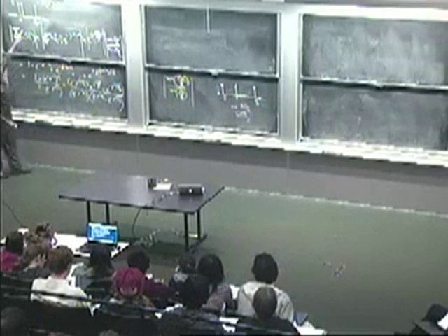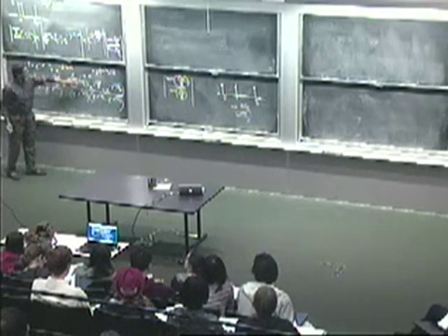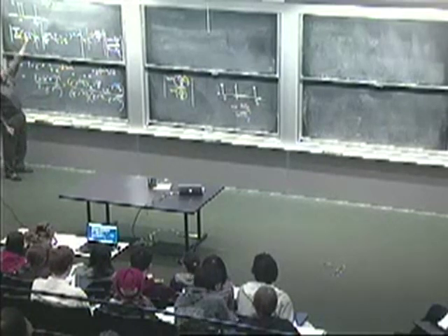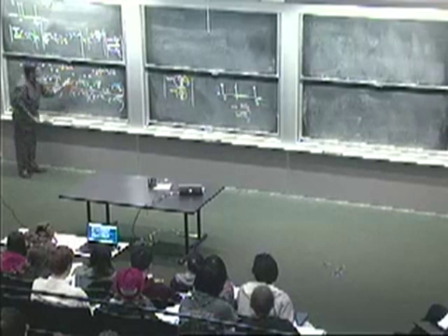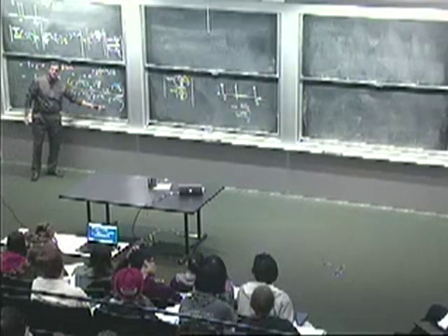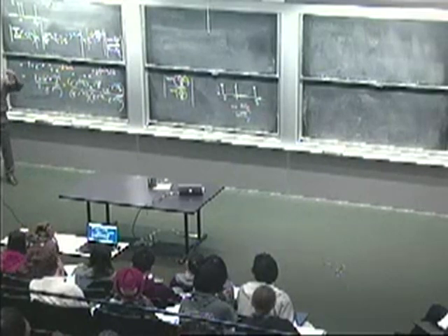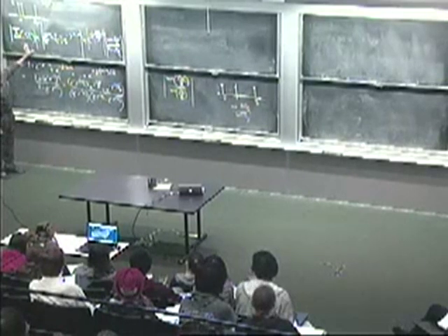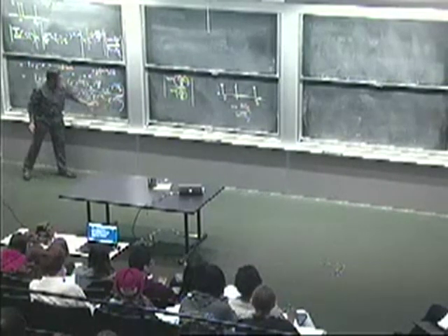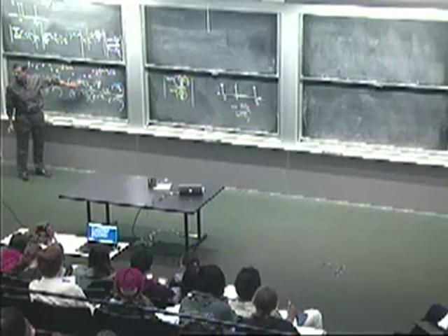Well, I did this for a case of a pulse starting at time 0. So this factor came purely from where I located this on the time axis. Different positions of this pulse on the time axis will modify this factor, but won't touch this factor. Shifts in time correspond to multiplication by e to the minus j omega something, right? You've seen that in a recitation. So whenever you shift the pulse in time, it leaves this part intact and affects this factor. But that doesn't change the magnitude of the transform.